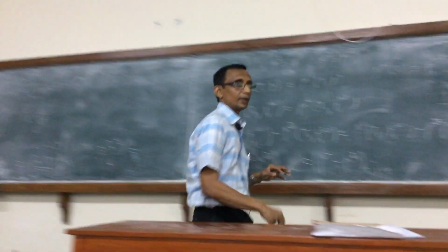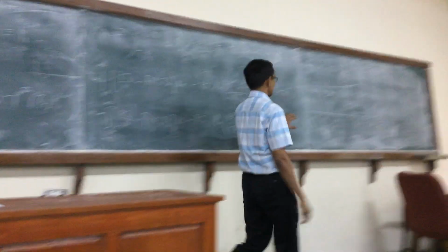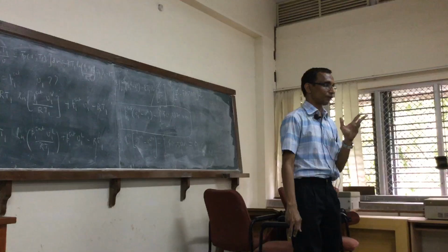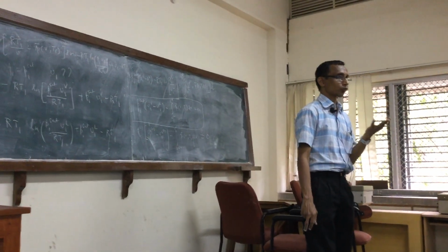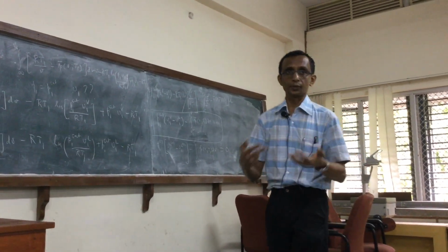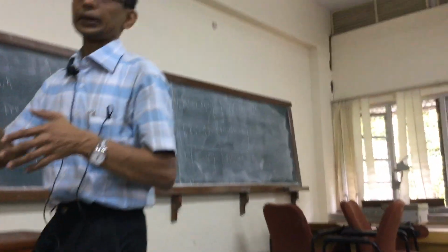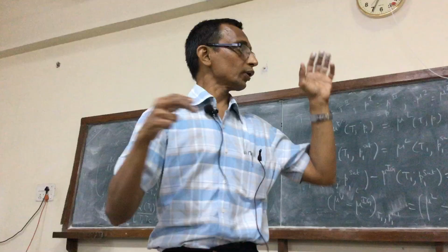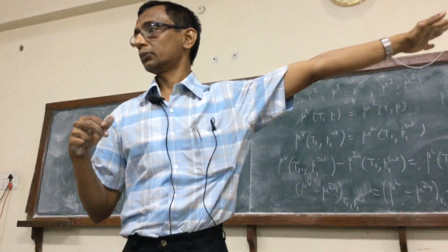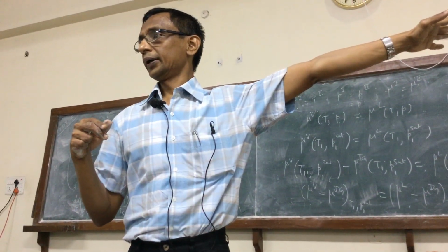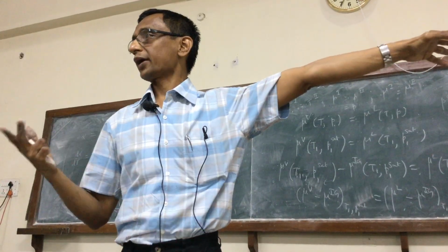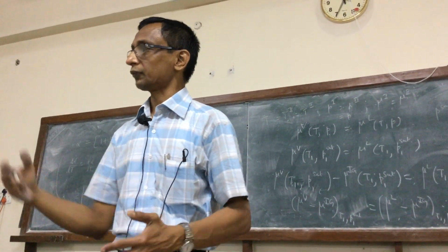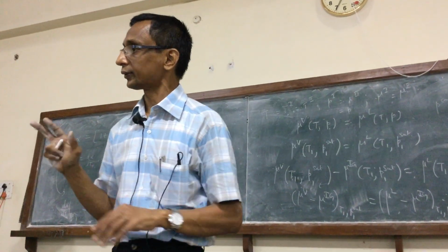So we have that. Once I have that, then I have to see whether those three quantities that I have now calculated satisfy the equation, one which I have assumed, the pressure, and the fourth quantity, the temperature, is given to me. So I assume a pressure, then immediately the two volumes are determined. So I have to go and substitute it into that equation, right? And check whether the equation is being satisfied. If it is not, then obviously I want to choose another pressure between PA and PB. So we'll see how to do that in a systematic manner.